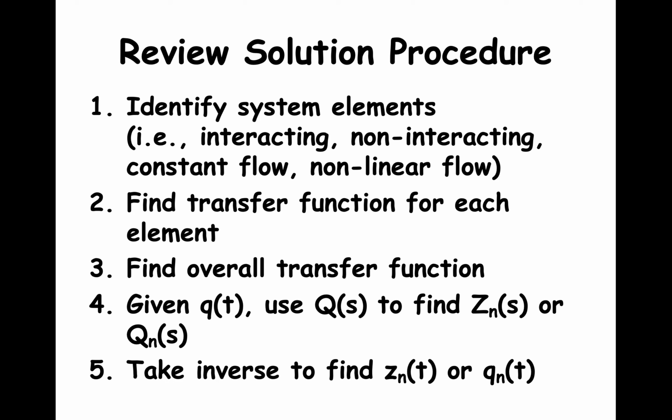You will need to be given either the time domain input function q(t) or the Laplace domain input function q(s). You will use the overall transfer function and the input function to find the Laplace domain expression for the desired liquid depth or outlet flow rate. Finally, you will need to take the inverse of the Laplace domain expression to find the desired time domain expression.